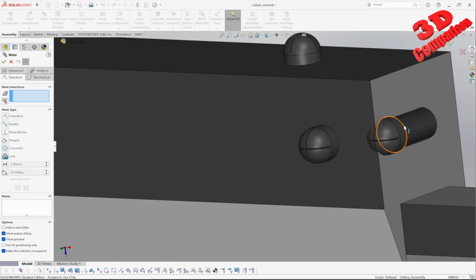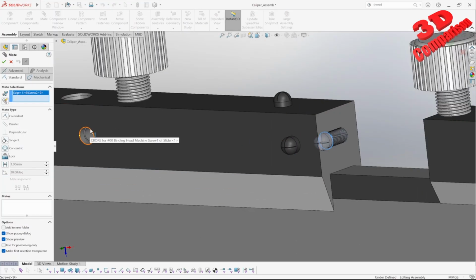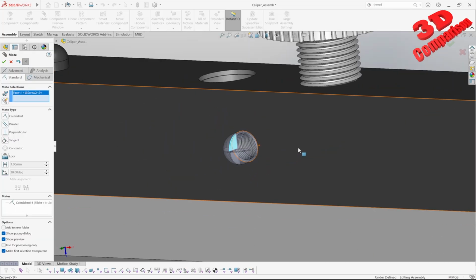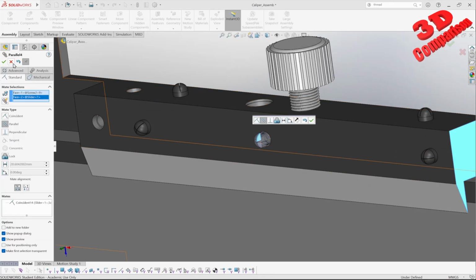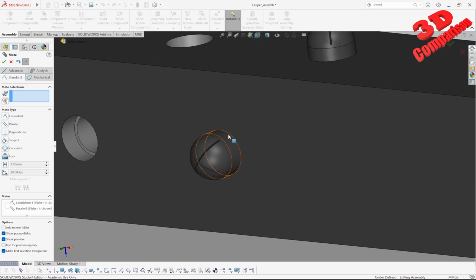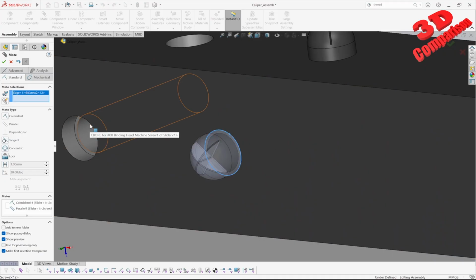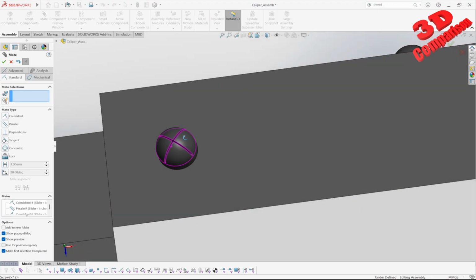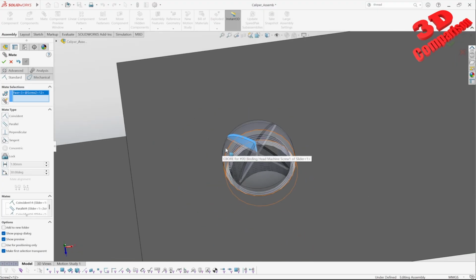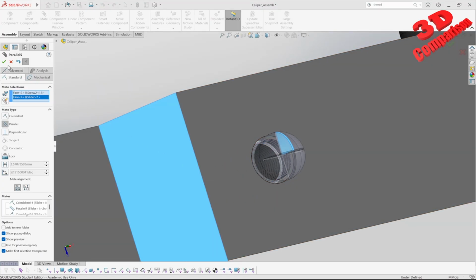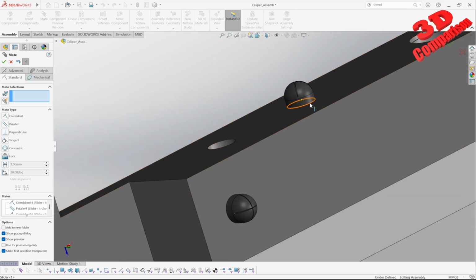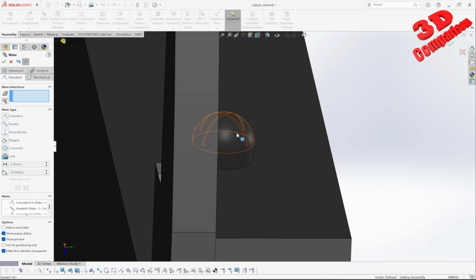So it's important that initially we center that location, and only after that we lock that tight fitting over here. Okay, we're going to have the following one. This is usually why it's a good idea to initially assemble the slider and have it slightly offset, so you no longer have to select those profiles, which is a little bit more complicated since they will be overlapped. It will be a lot easier.